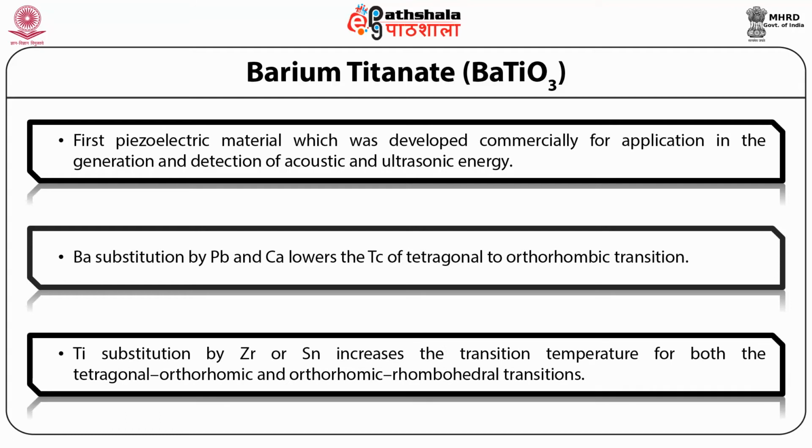The titanium substitution by zirconium or tin increases the transition temperature for both the tetragonal and orthorhombic to rhombohedral transitions, and enhances piezoelectric properties.